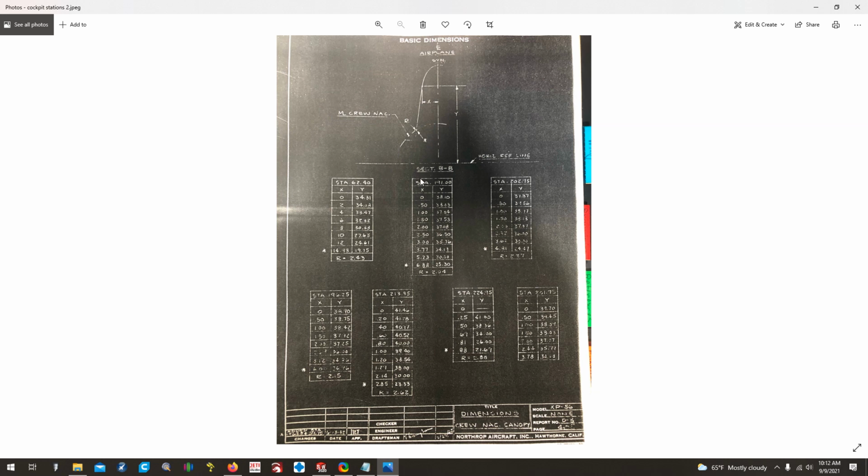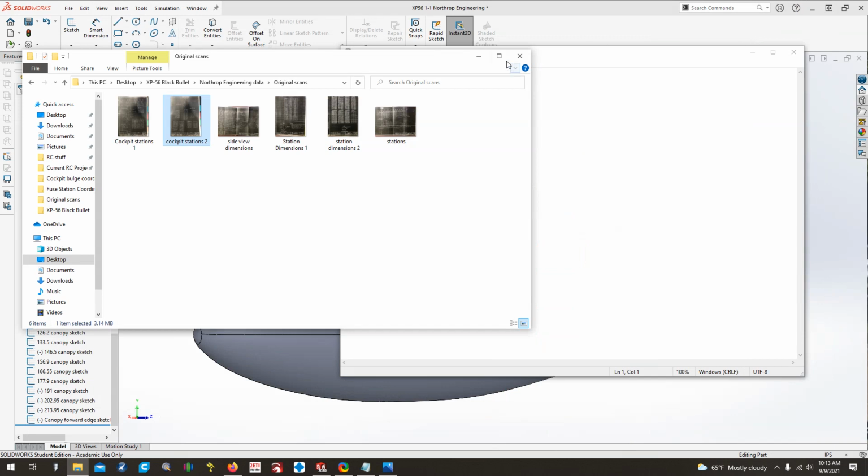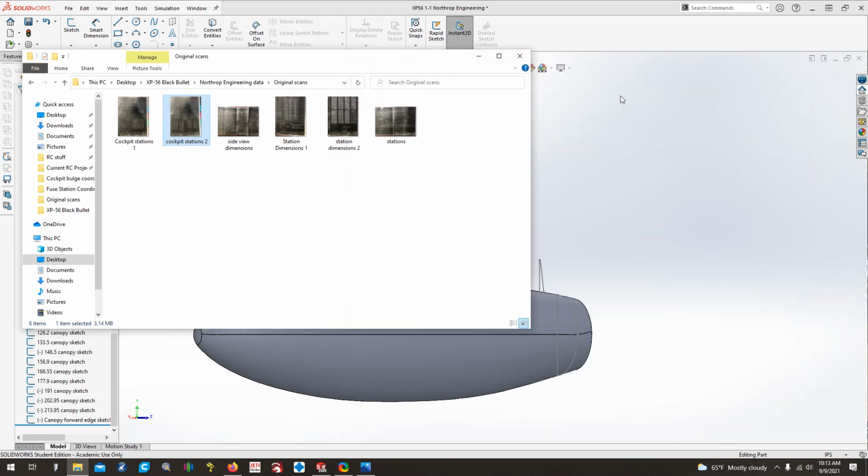You'll see the asterisks at this point, X 1498, Y 1975. That point should be coincident with the outside surface of the crew nacelle or the fuselage. In other words, it should meet our fuselage cross section that we drew.